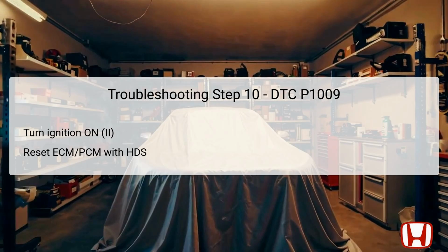This reset is essential after any repairs or adjustments to ensure the computer system accurately monitors the vehicle's current operational state. Following the reset, you will proceed to conduct the ECM/PCM idle learn procedure, which assists in updating the module's adaptive learning values for optimal engine performance. In this step, perform the ECM/PCM idle learn procedure after resetting the computer. This procedure helps recalibrate the ECM/PCM's parameters to optimize engine performance by learning the engine's idle characteristics.